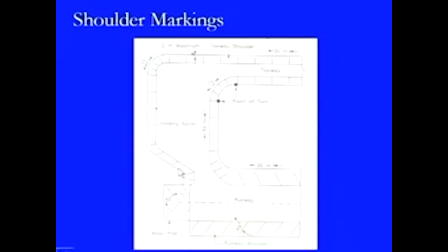form. Then here what we see is that the angle conditions still apply. That is the part of the runway, and as soon as it comes to the holding apron, they become perpendicular to the edge. So, we can look at these perpendicular strips being provided, and at the maximum they can go up to a distance of 1.5 meters, like this one. And here this is the point of turn, and in between these points of turn it is located at a distance of 15 meters. So, this is how they are being located here. From the edge it is 1.5 meters from this side.